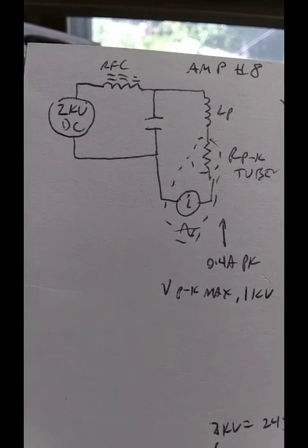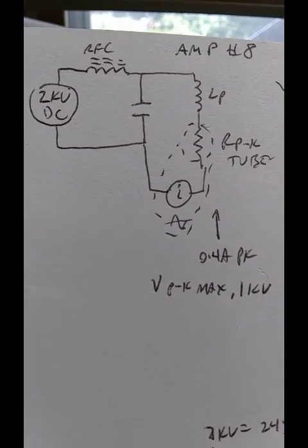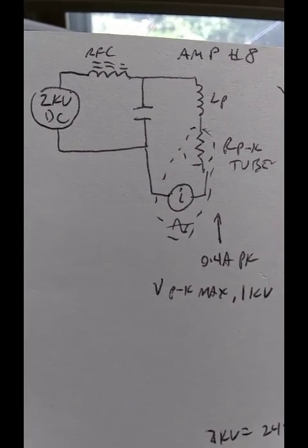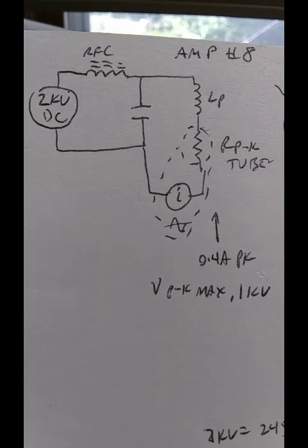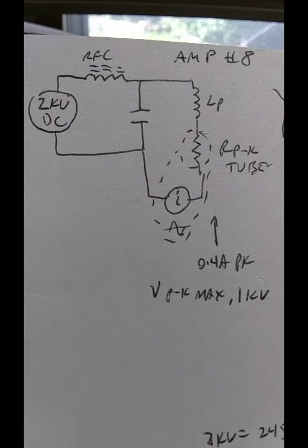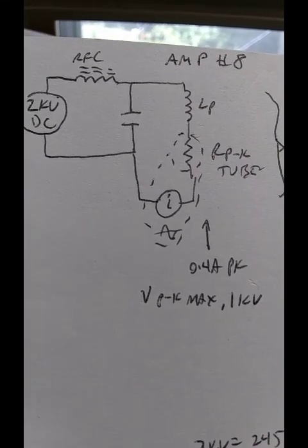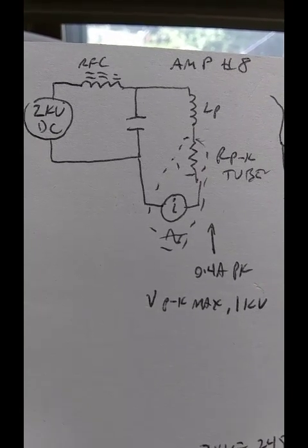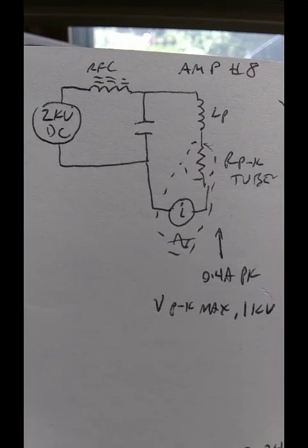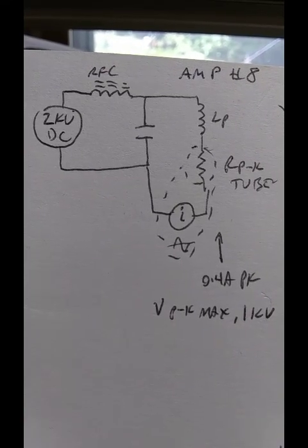It works. It's a law. It can't fail. What we've got to remember is that the inductor is also a voltage source. Charge a capacitor, remove it from the circuit, it's a current source. It's stored energy that can become current. Charge an inductor, attempt to separate it from the circuit, and it will make an arc in a desperate attempt to continue the current to discharge.